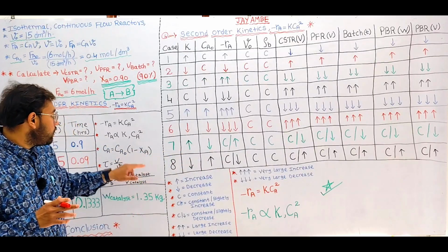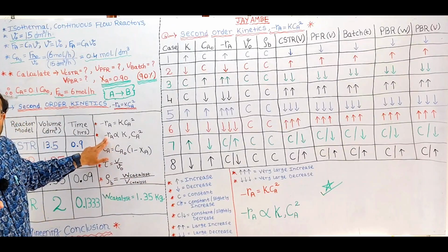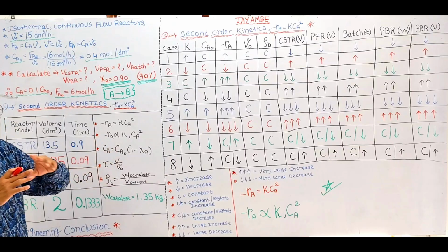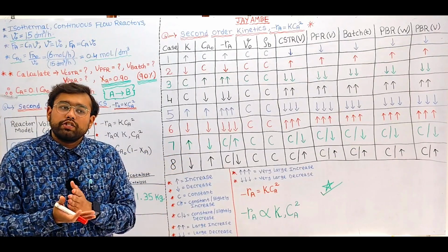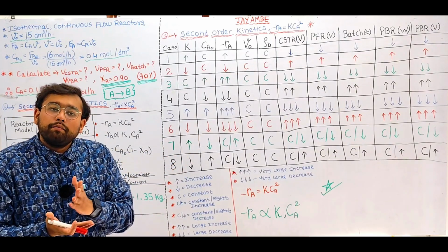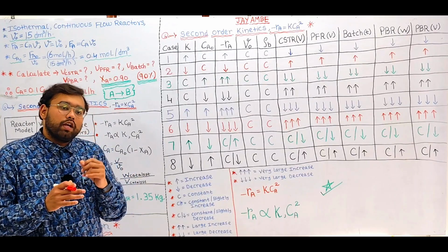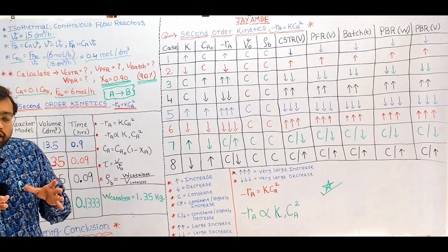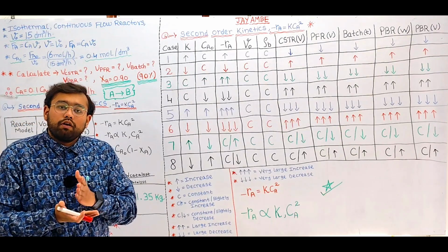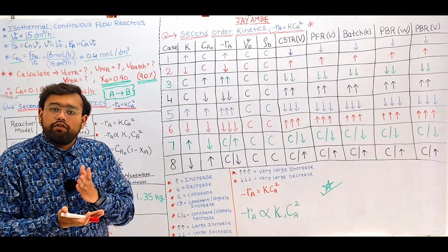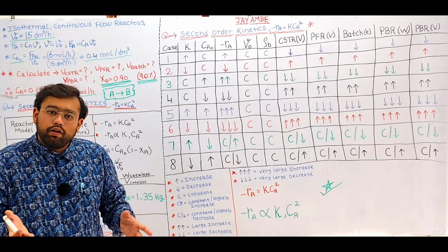Due to which the rate of the reaction will also decrease, slowly and gradually, right? At the outlet stream of the PFR, the concentration of the reactants is minimal or there is none, which means, as in the case of a batch reactor at the completion of the reaction, where we have minimal unreacted reactants or no reactants present, right?